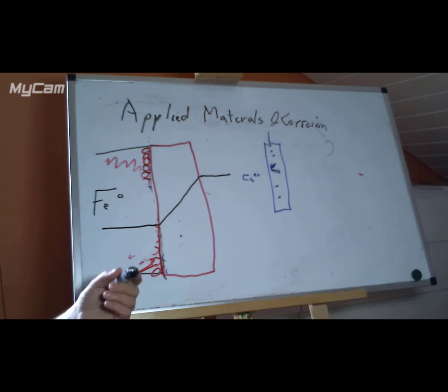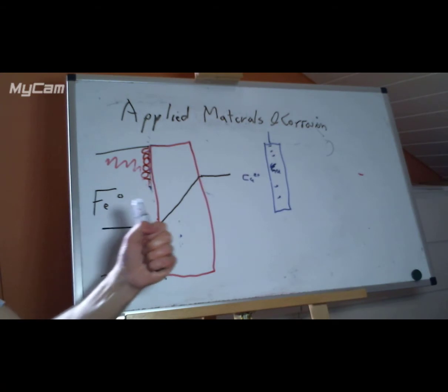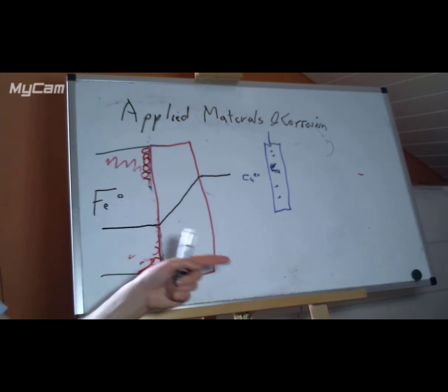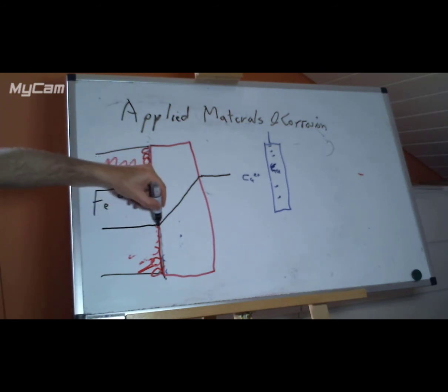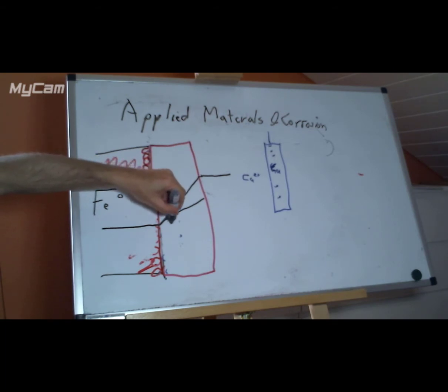So if we heat it up, the ions have more energy and the lattice has more energy. And as you'll know from either metallic materials or non-metallic materials, they're moving around inside their positions in the matrix, and they can squeeze through. Interstitials can pop through more easily at higher temperatures, which would mean that we would expect a lower angle because the resistivity determines this angle.